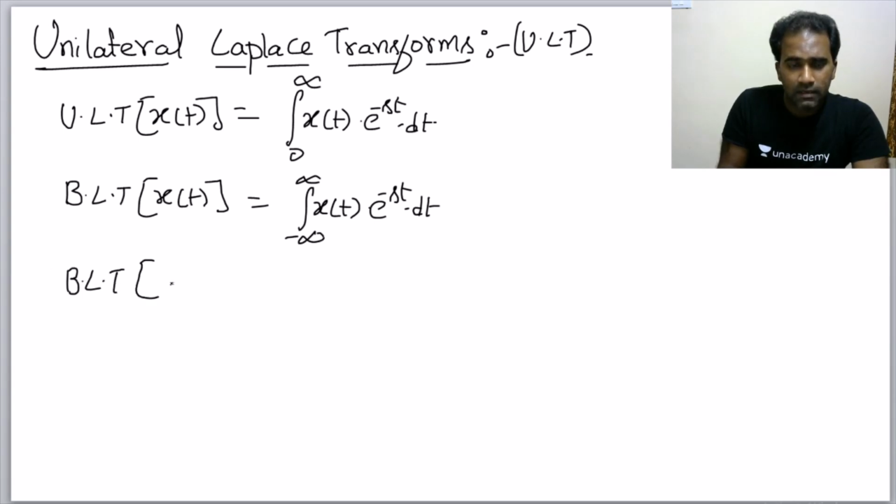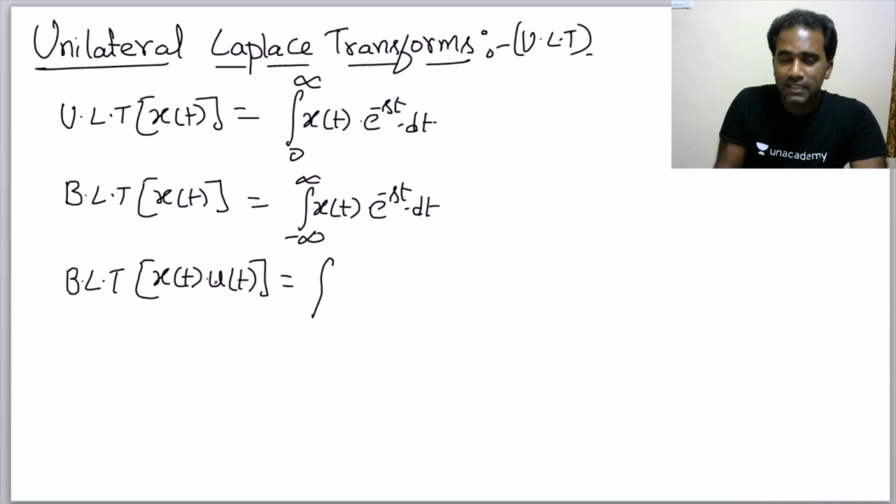How about the bilateral Laplace transform of x of t into u of t? If you multiply the signal with u of t, you are limiting the signal only to positive time. You are removing the negative time part of the signal, not the negative amplitude part. So it is minus infinity to plus infinity, the same formula, but applied on x of t into u of t into e power minus st dt, which is equal to...